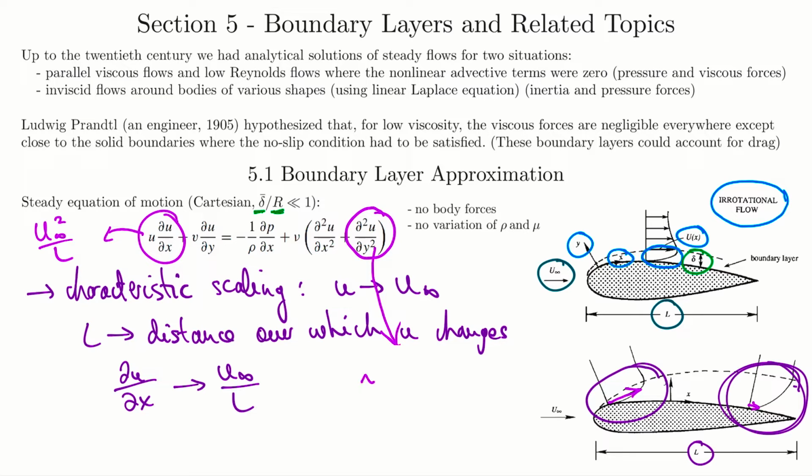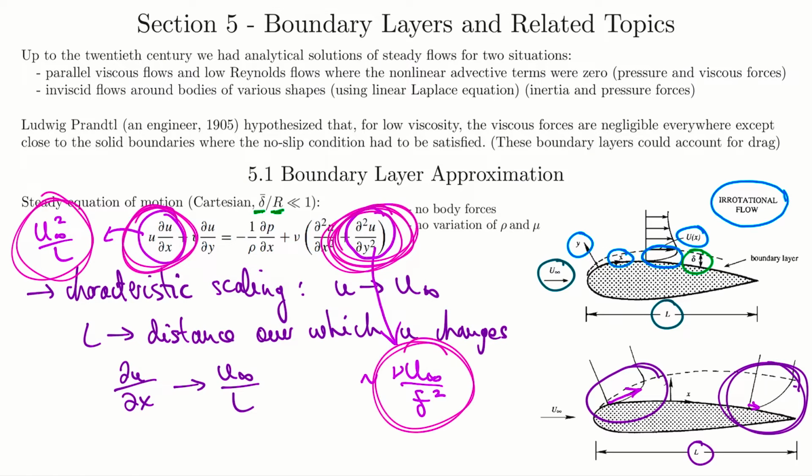The viscous term here will scale like, we usually use this to say that it's of the order, this. And we use delta bar as the characteristic length in our y direction, which is the average boundary layer thickness. To find the scaling of our boundary layer thickness, the argument we make is that this advective term and the viscous terms over here have to be roughly the same order of magnitude within the boundary layer if the viscous terms are to be important. So comparing these two expressions with our scaling, we rearrange to see that our average boundary layer thickness, delta bar, is approximately this.